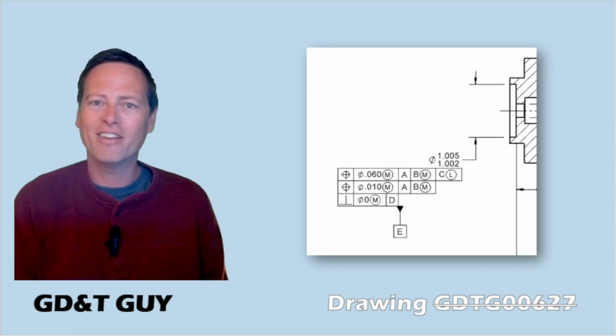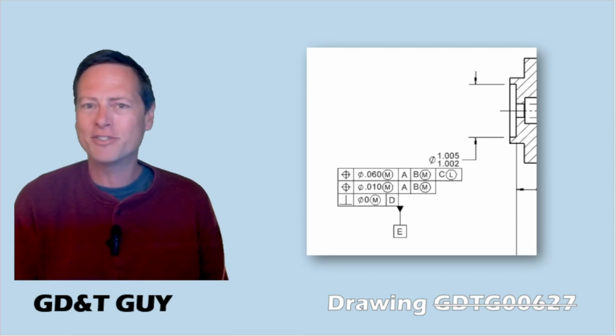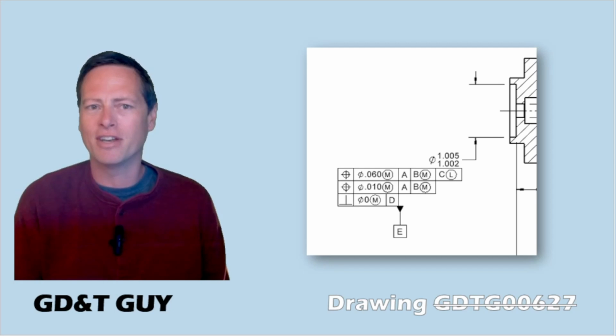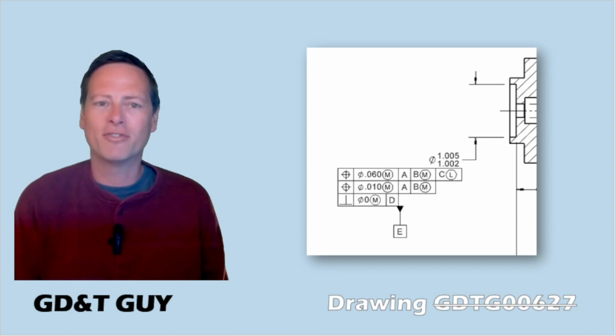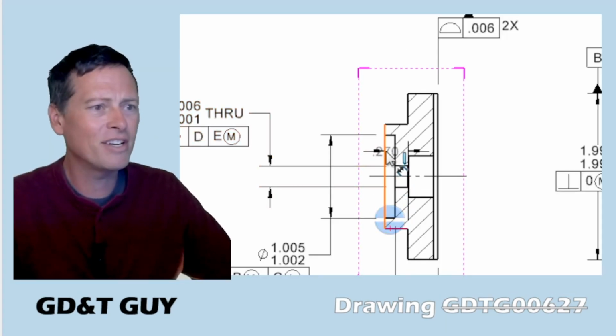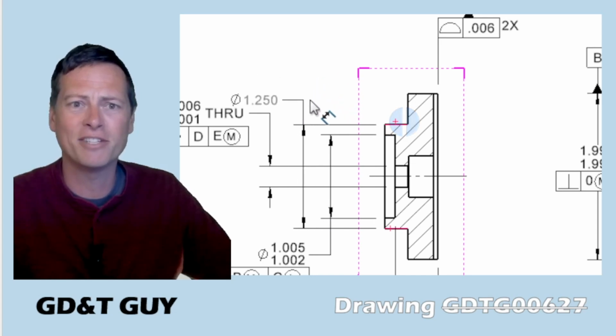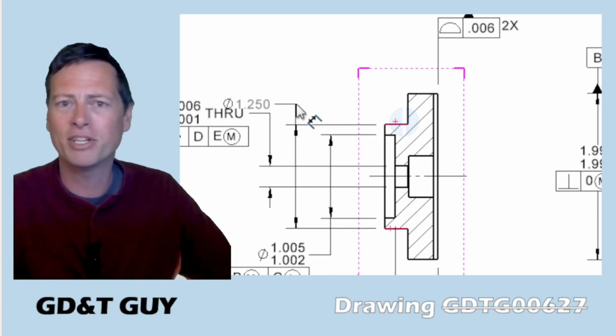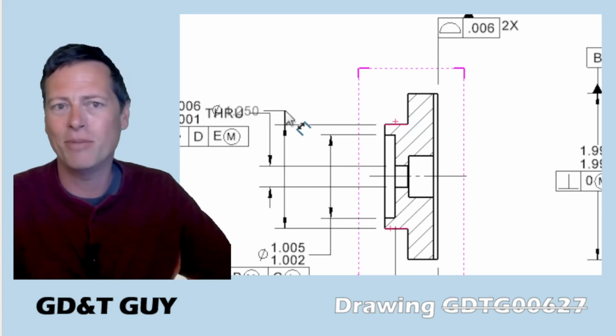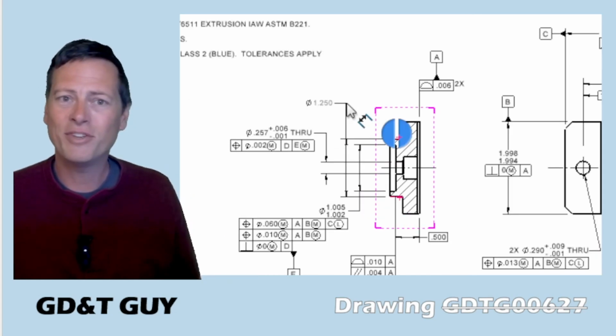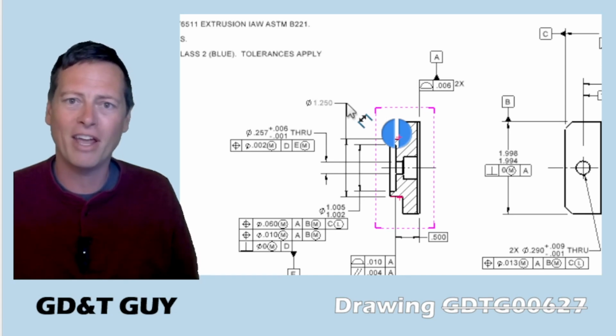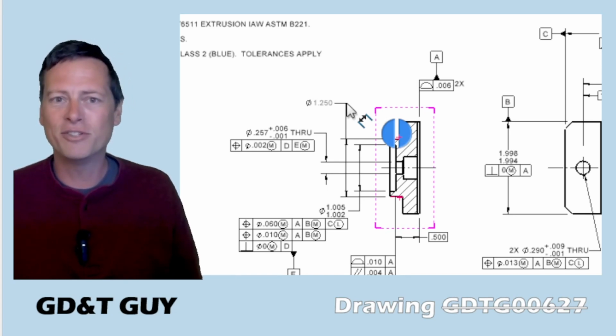And the more I thought about it, having the datum C could open up some other interesting possibilities like multi-segment position on the 1-inch diameter feature. This would put a looser tolerance on the position of that feature in X, as we've been calling it, or left and right along datum B. That's pretty cool. But getting pretty deep in the weeds here, then you would want to make sure that this outside cylindrical feature is located to the 1-inch diameter feature and not to the ABC datum reference frame. And if you do that, it should probably also be an LMC type of deal, or you could lose control of your wall thickness. Good grief.